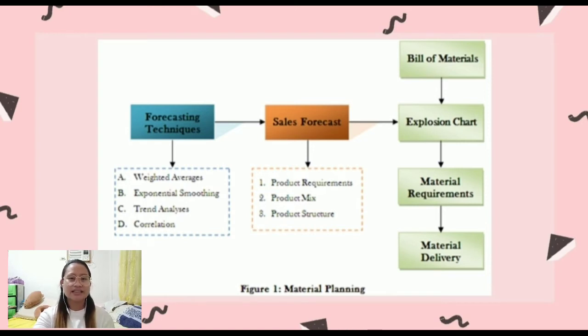Bill of materials is a document which shows list of materials required to unit consumption location code for a given product. An explosive chart or an explosion chart is a series of bill material grouped in a matrix form so that combined requirements for different components can be done, and various materials are arrived at from the demand forecast using bill of materials through explosion charts.